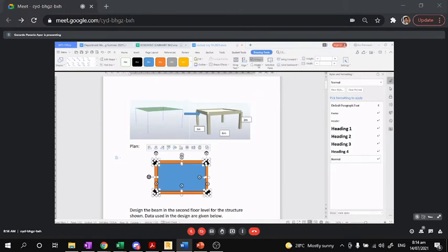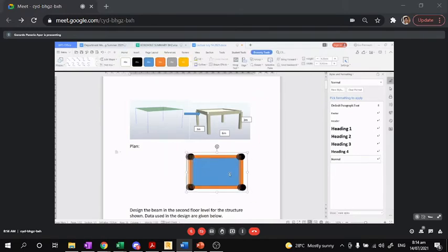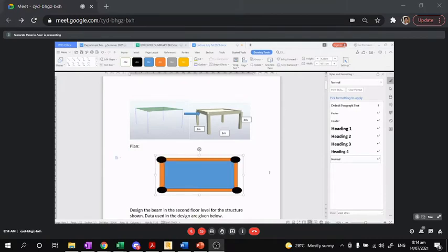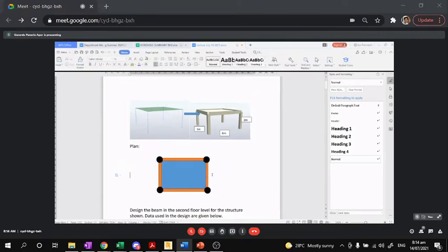Group. Okay, so the group na siya, no? So the group is one. Now I intentionally make the other side longer and the other side narrower, no? Because these are the system. These are the most common, no? Now you can even make that a lot narrow or rectangle. It depends, or you can make it a square. So it depends, no? But the square configuration of plan, it's more of two-way slab. But if it becomes rectangular like this, you can call it one-way slab, no?